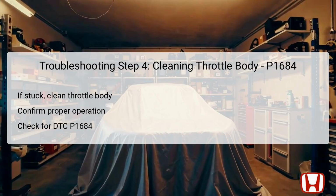If the throttle body inspection reveals a stuck condition, the next logical step is thorough cleaning of the throttle body. This involves removing any carbon buildup, debris, or other contaminants that may be obstructing the valve's free movement. Post-cleaning, it is essential to perform a confirmation procedure to check if the DTC still remains.